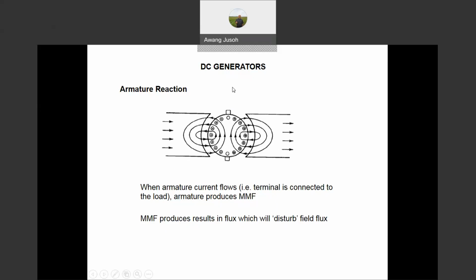In this DC machine, basically, the angle between the D and Q flux is always 90 degrees. That means at any moment, the machine always produces maximum torque. That is why this machine is very good in terms of torque production, compared to the AC machine. And the fluxes are not coupled to each other: the D flux is not coupled with the Q flux, which is the flux from the armature circuit. That is a very good thing. We explained that before.